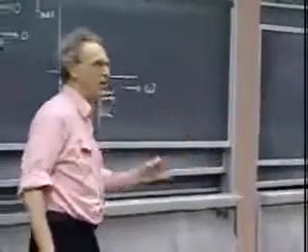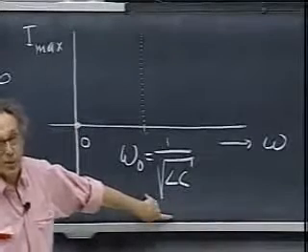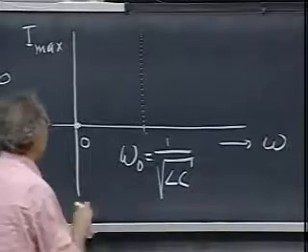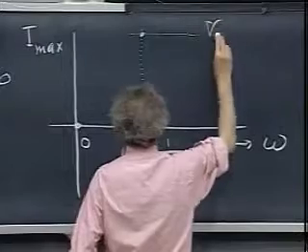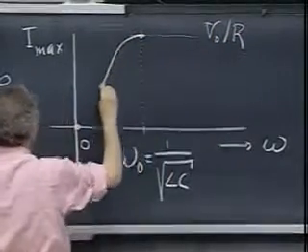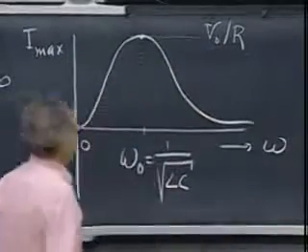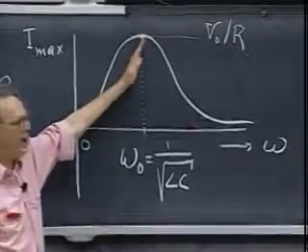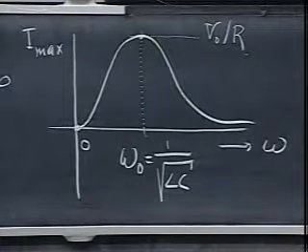It's really determined by L and C, because it is the X that you want to make 0, and X is only a function of L and C. At this frequency, we have a value here, which is V0 divided by R. And so the curve that you're going to see, which we call the resonance curve, is something like this. You start out with an extremely small current, you go through resonance, we have a high current, and then at high frequencies, again, you go down to 0.